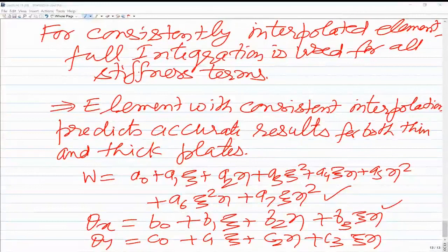You have two different sets of loops for getting the bending stiffness and the transverse shear stiffness. In the transverse shear stiffness evaluation, just change the loop variable and things are done. Programming-wise it is much easier, and computationally you would be evaluating at a lesser number of Gauss points, so the element level calculations are lesser. That way, the reduced integration or selective integration technique is preferred.